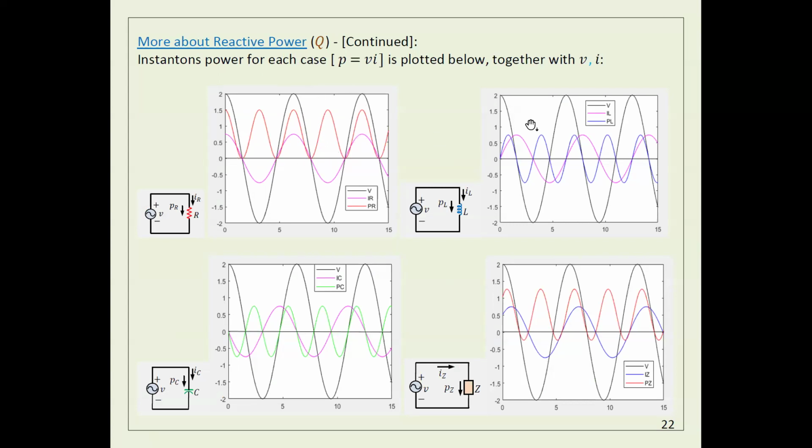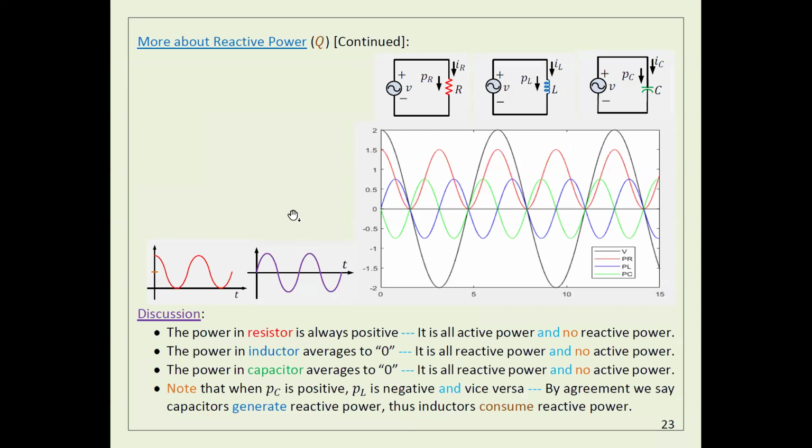But there is something important here, and it's related to what I told you about power factor correction. At home, if the power factor is far from 1, I have to add an inductor or capacitor to bring it back to 1 to reduce losses. That is, to reduce the reactive power, and that's what we call correction. There is something interesting here. I will show you.